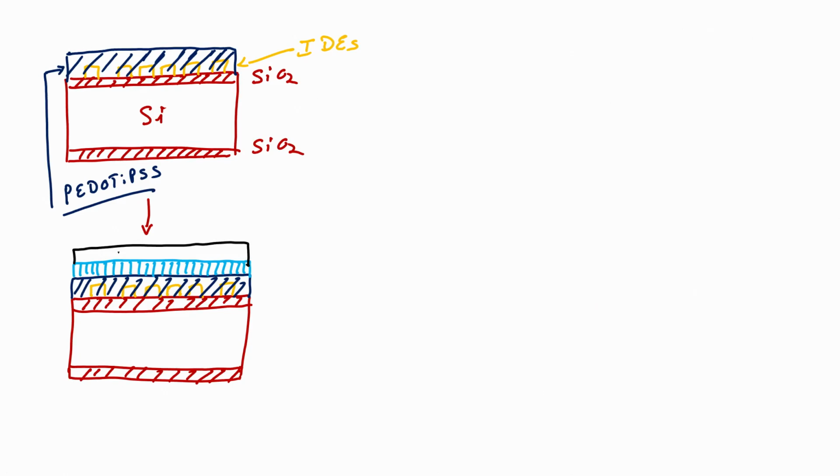For that we need a mask which will protect my piezoresistive material in the desired area, and that will help me to pattern the piezoresistor. This is my bright field mask.